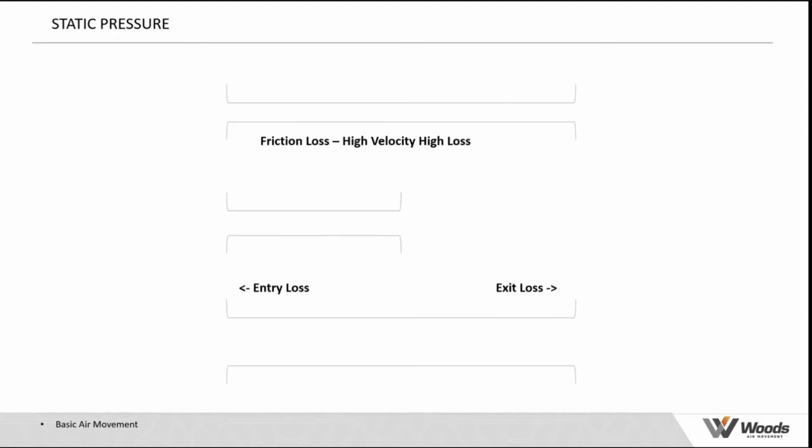And it all makes sense, really. If we're trying to push the same amount of air through a number of different systems, if we've got a small duct and it's very long, we get much higher frictional losses. If we shorten that duct, bigger diameter, we reduce the inlet and outlet losses and the frictional losses. And if we've got a very big duct for the same volume, then our frictional losses really come down. Just nothing more than common sense.